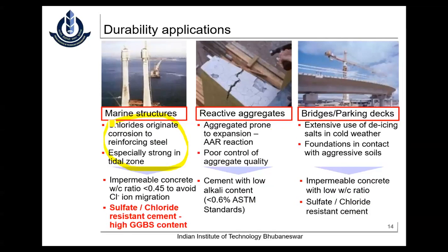We have proven that. We have enough data from my own lab itself. We can go for sulfate resistant cement, which has a GGBS of more than 60-70%. You can go ahead without any hesitation. You can go and use that cement.